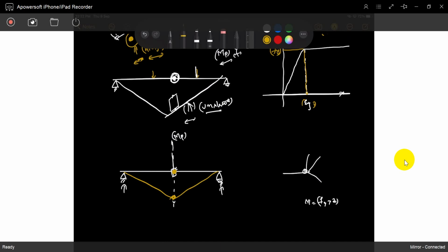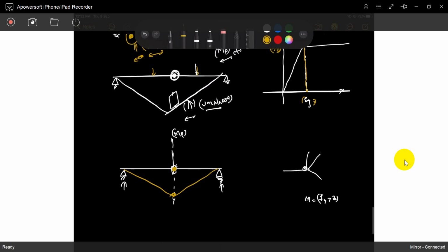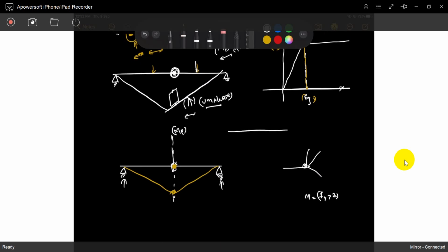It is unstable, na? It is unstable, you already know it. If there is a hinge inside, it's unstable because there is no load carrying capacity of that section. It is a hinge, it will turn. It's just a weak link. Otherwise, if it is not a hinge and load is applied, it will go like this, that's it.